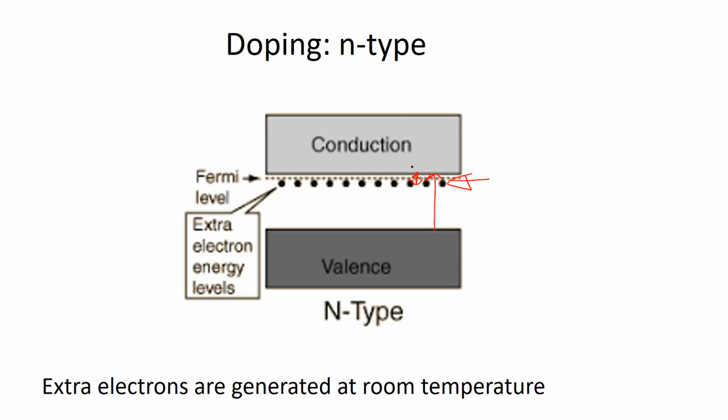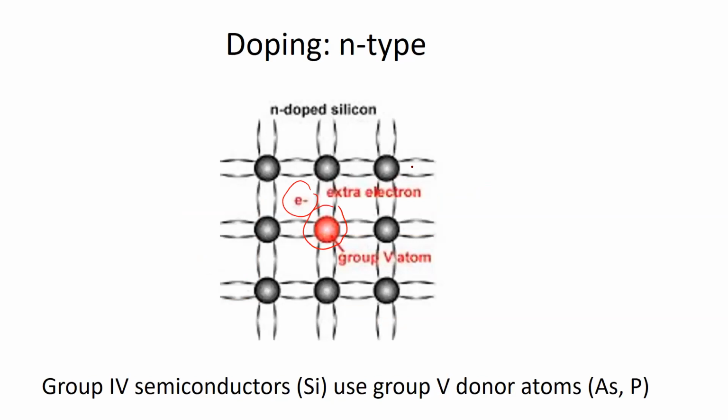And doping is a really important technique because it allows a semiconductor to exist which has more of one type of carrier than the other. Note that when doping silicon with arsenic, only excess electrons have been generated. It's also important to understand that the charge associated with arsenic atoms is actually positive. Firstly, since the arsenic atoms have donated electrons to the silicon semiconductor, we call them donor atoms.